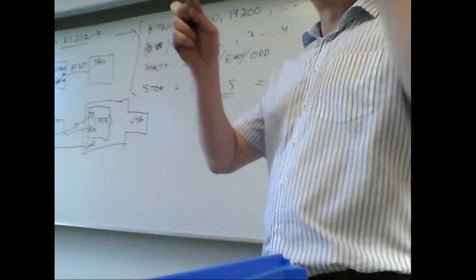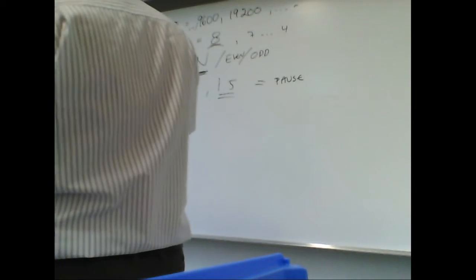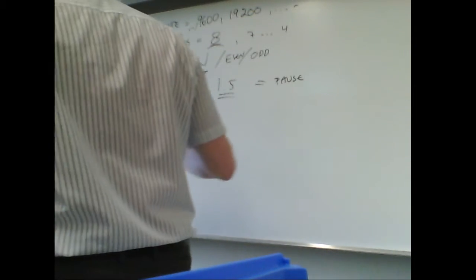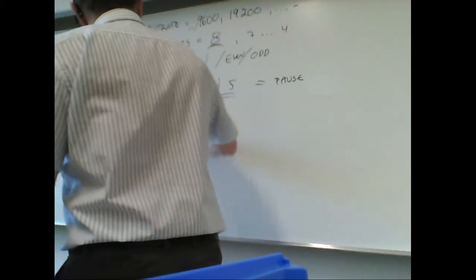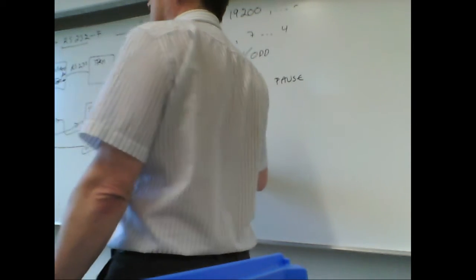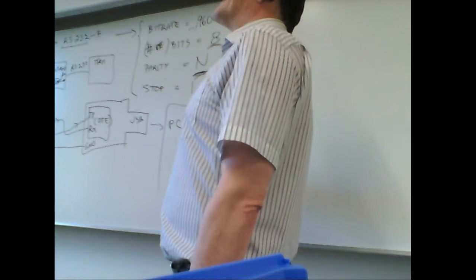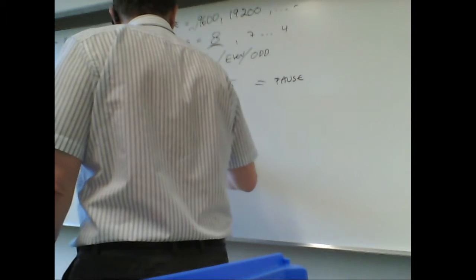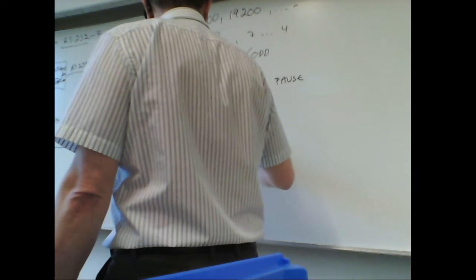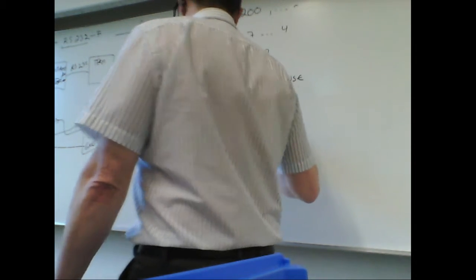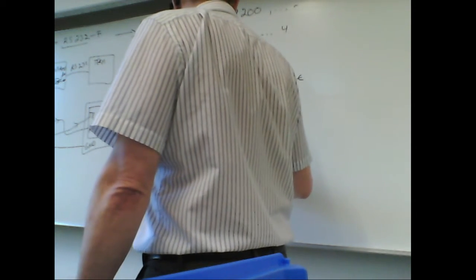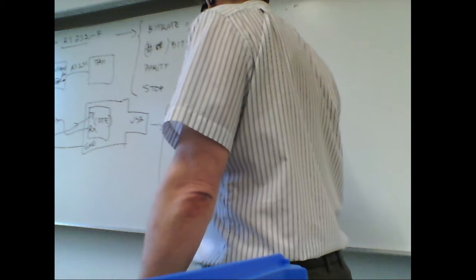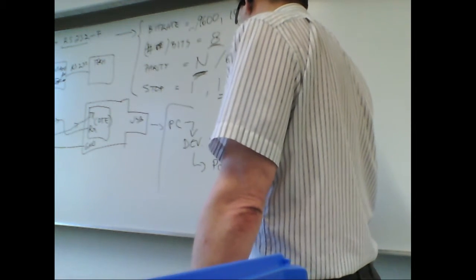How do you know the parameters here? Since this is, you know, kind of a debugging device, when you plug that one into the PC, then you go into the PC and take the, let's see, the device manager. You can actually then see the ports, and on ports you will find a COM port.